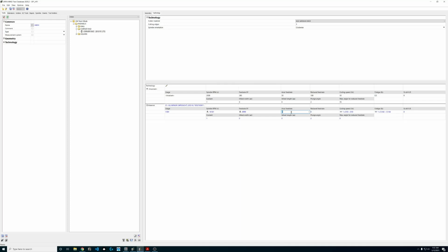So if I know that I have good code and a good tool path and my end mill isn't just going to be plunging into the material, I might just use my feed rate formula here. I might use my feed rate formula multiplied by some factor because I want to meet that G0 with a really fast feed move to get my tool back to the workpiece as quick as possible. For now, because we haven't defined much else, I'm just going to go ahead and use the feed rate function. Reduce feed rate. So this is something you have to play with a little bit.